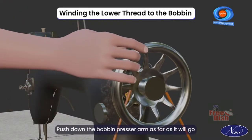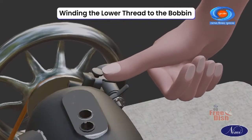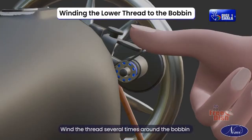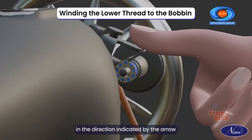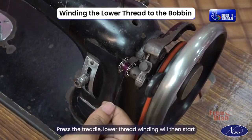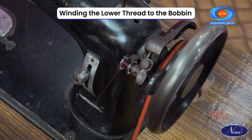Push down the bobbin presser arm as far as it will go. Wind the thread several times around the bobbin in the direction indicated by the arrow. Press the treadle. Lower thread winding will then start.